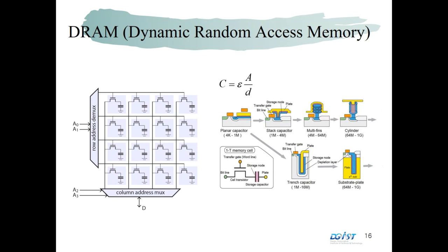the DRAM consists of one transistor and one capacitor. And when we scale down the size of DRAM, the capacitance of the capacitor will decrease. In order to prevent such a decrease, they make a very complex structure to keep a certain amount of capacitance. So they made a very deep trench. That's the very difficult part in a DRAM process.